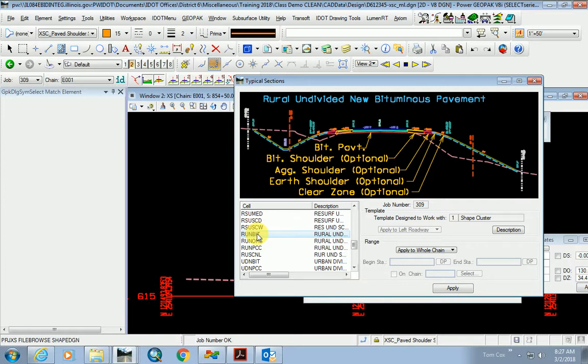I just found over the years that no matter what you do with this, this system is really, really good for automating 80% of your cross-section of the work. And it seems to me like no matter which one of these you choose, you still end up manually drafting about 20%. And I know that this one, new construction, works really well. And even though on the main line I'm not replacing the pavement like I am on the side road, because everything's on its own level, I can go in and, with the click of a button, delete the pavement. That's what I do.